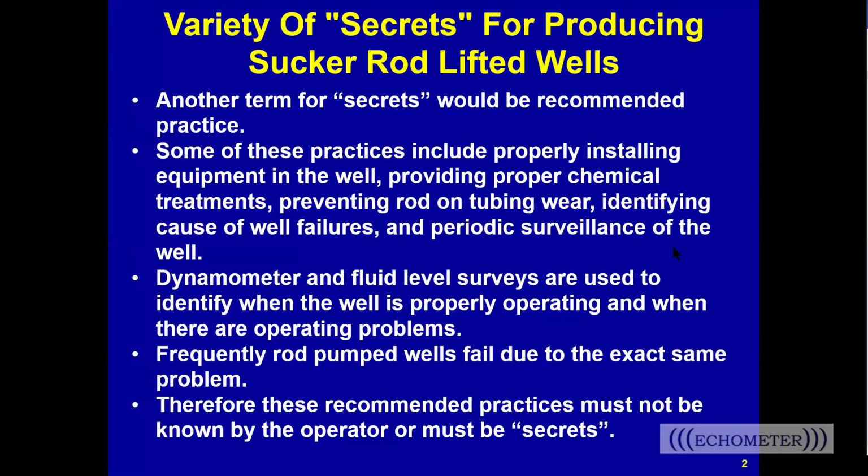Next, we're going to talk about secrets. When we talk about secrets of rod pumping, sometimes people say, "Didn't you know it was a recommended practice to have your pump filled with liquid?" And someone will say, "No, we hadn't heard that before." So the term secret may be a little broad here, but what we're trying to say is that there are recommended practices to operate sucker rod lift wells, such as proper chemical treatment for corrosion, preventing rod on tubing wear, doing failure root cause analysis, and then monitoring your well's performance.